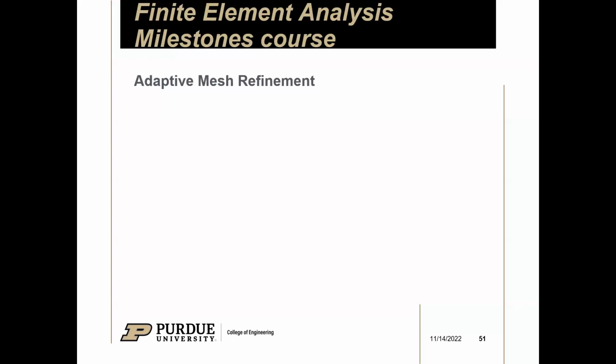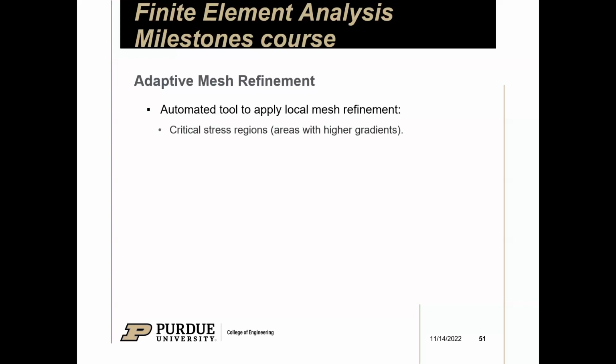This is particularly helpful when you're analyzing critical regions. Let's say you're analyzing a crack in a model. You can accurately see how much displacement and how much stress is applied to that specific crack using adaptive mesh refinement. So moving on here. Yeah, so here it is.